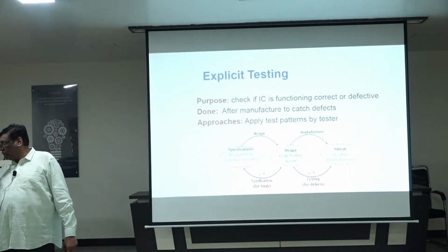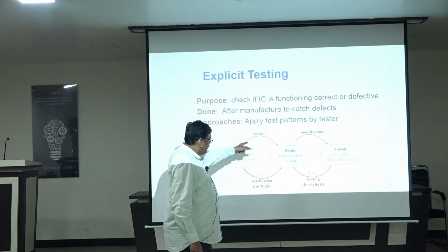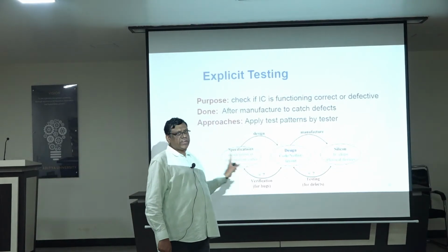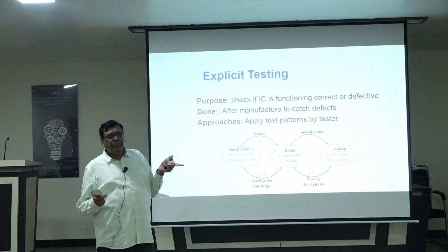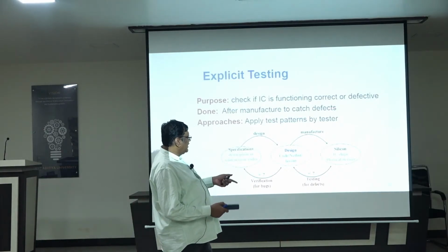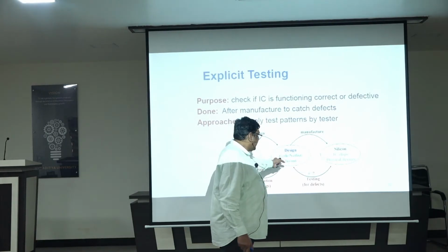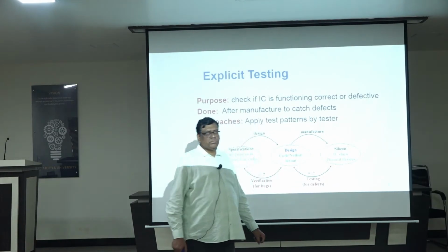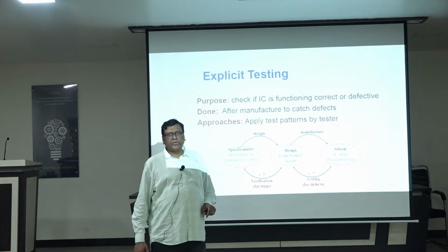Next. So there is a specification, then we go to the design. Whether this specification and design are the same or not, we check using verification. That is design verification; ModelSim is a very popular tool for it. What is testing? After the design is done and silicon comes, that means manufacturing is completed. At that time, whether the design and the silicon are the same or not is called testing. Simply put, verification is different, testing is different.